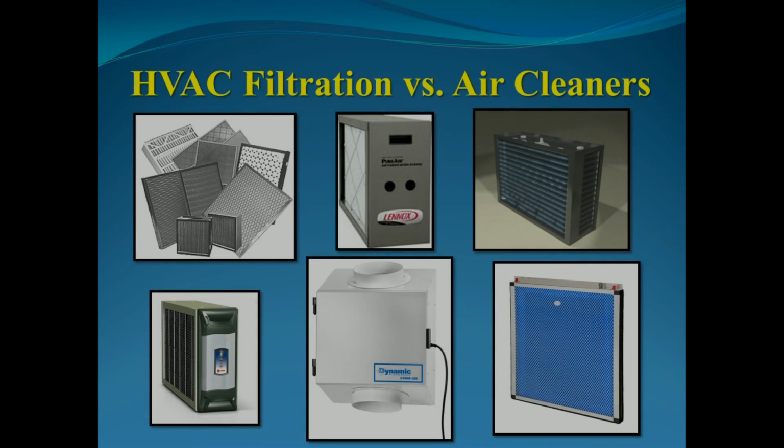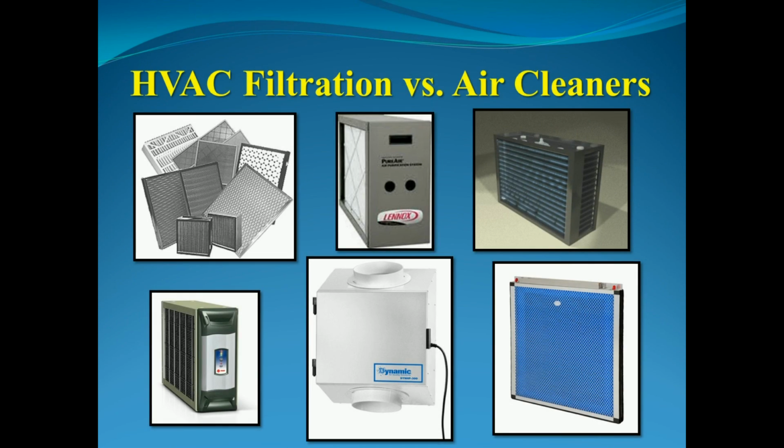And let's talk about the difference between what a filter is and what an air cleaner is, because there's a substantial difference when you look at what it can do. And a lot of confusion from what I hear about with technicians today. That's correct, absolutely. So really what you get down to is we've got all kinds of different filters on the market. We've got passive filters. We've got the pleated filters, electrostatic filters, all the stuff you can buy at the Home Depots and the hardware stores today. And then we've got air cleaners too. And there's a dividing line.